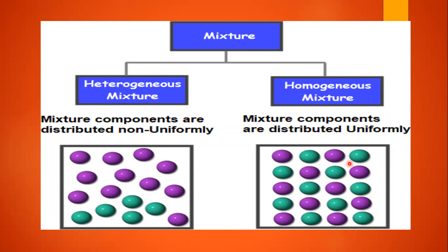Then we are going to have the equivalence ratio. The equivalence ratio is denoted with phi. Phi is equal to the actual air-fuel ratio divided by the stoichiometric air-fuel ratio, like 1 is to 17 over 1 is to 15. Finally we get 15 by 17, which is going to be a lean mixture, right? So now the equivalence ratio is less than 1.